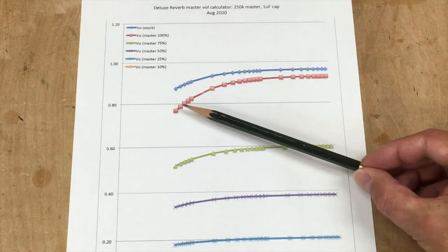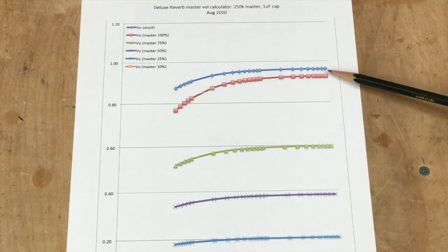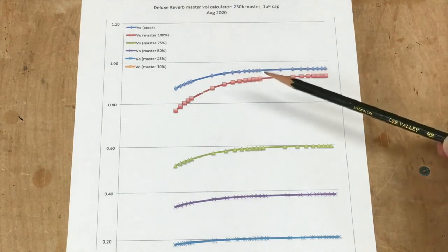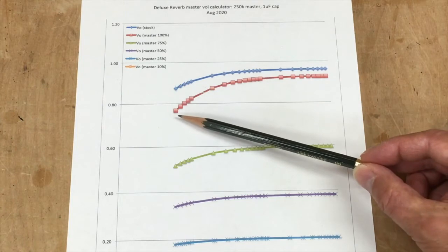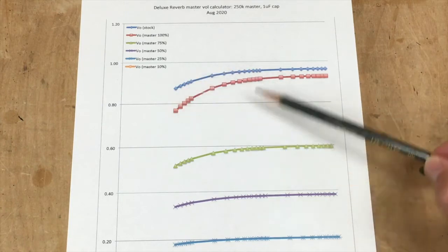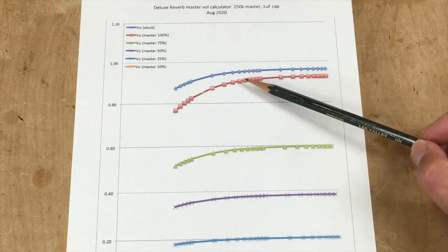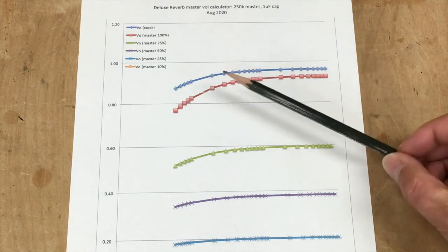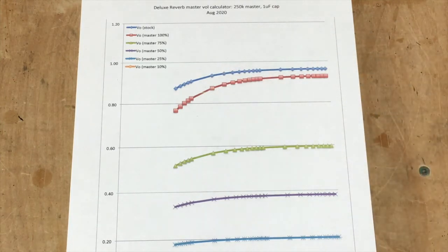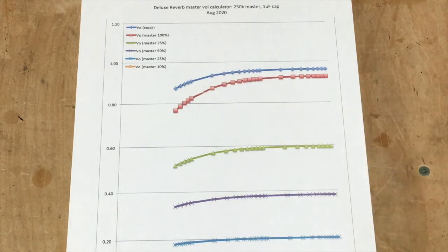Now you can see right here that even when the master is all the way up, the response is not the same. You've got a little bit of voltage loss, but more importantly the shape is not the same. In the lower end, this particular circuit is going to sound thin because you have quite a large reduction in your bass response. And so this is rejected. This will not be used. However, we have some more parameters to play around with to see if we can match the response that we want out of the stock amplifier.